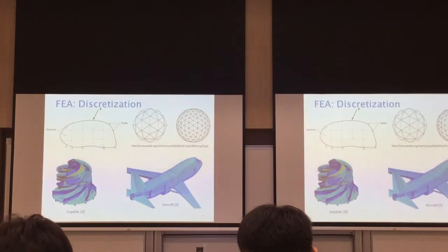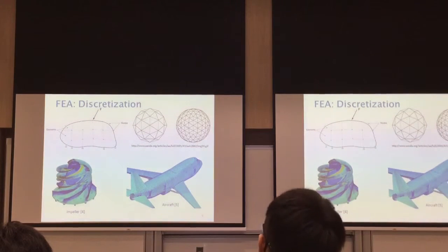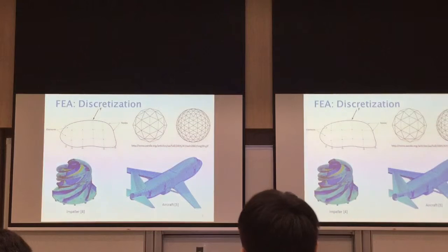If it's an approximation, then definitely there will be errors. So what we have to do is, of course, to use different elements. The higher the order, the better, but that will also cost a lot in computational time. Use more elements: the more elements you have, the bigger the stiffness matrix you're looking at, the more equations we are going to consider, and definitely that will increase the computational time.